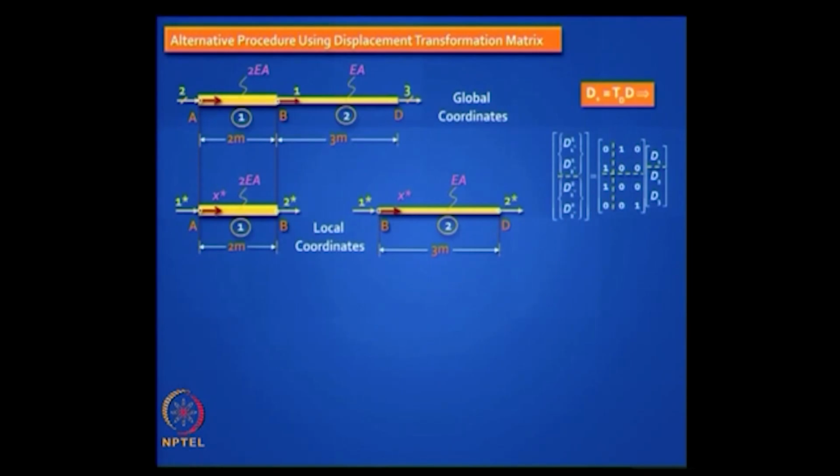Why do we say that? So take a look at this. This is your TD matrix. To fill the first column, and mind you there are two elements, this belongs to the first element, this belongs to the second element, you apply D1 equal to 1, which means if I put a unit displacement here, what gets affected? Well, this gets affected and this gets affected because they both connect to the same point, right? Does this get affected? Because you are applying only a unit displacement one at a time. Does this get affected? No, that is arrested. Does this get affected? That gets, so it's simple logic.